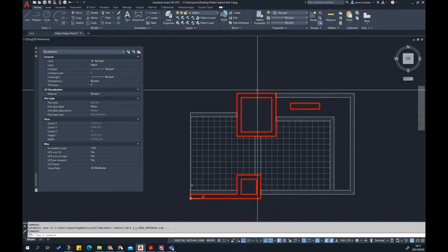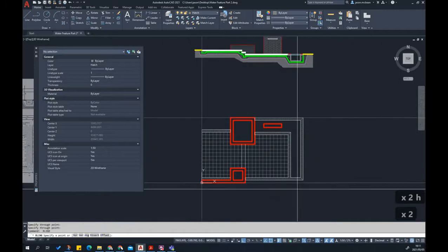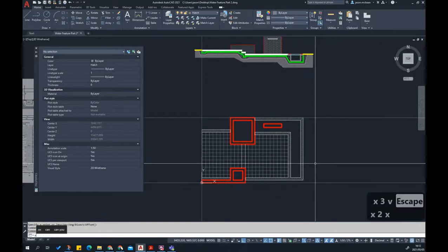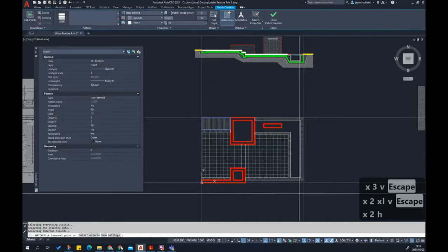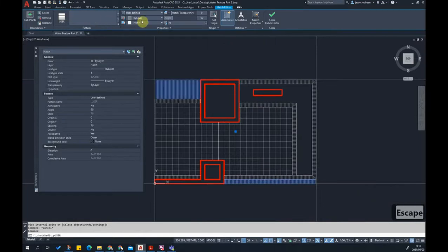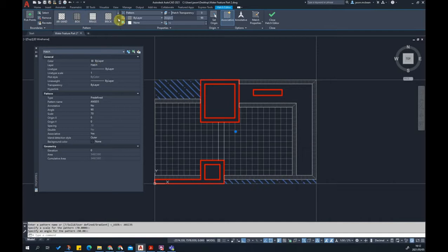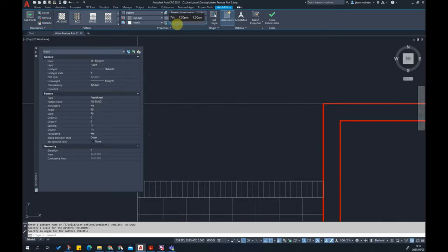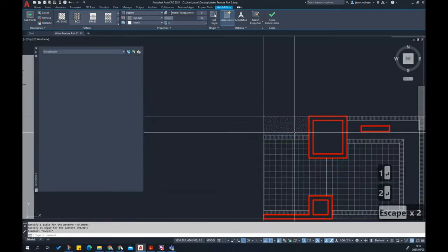Okay, now we can start introducing some planting. So X line, vertical, one there, horizontal, one there, because we're going to introduce some planting, one there, and vertical there. X line, vertical. And these I can just make one hatch. So I'm going to go hatch, I'm going to pick there, and there. This is just going to be like a sand layer, because technically it's planting, so we can just use a pattern for this. And I'll just go and find a sand pattern here. Sand, that's good enough for now. And that will be scale 1 or maybe 2. Yeah, because that's just planting.